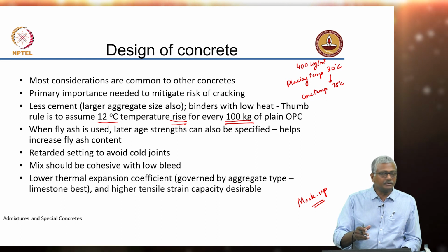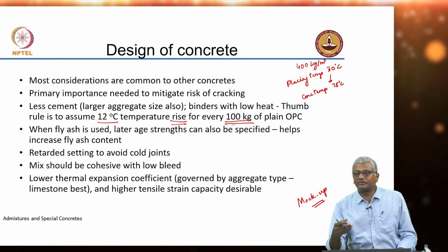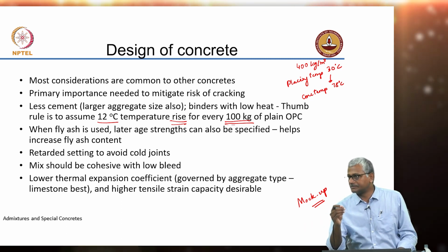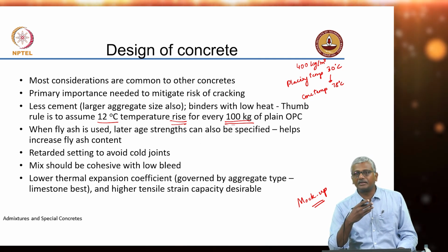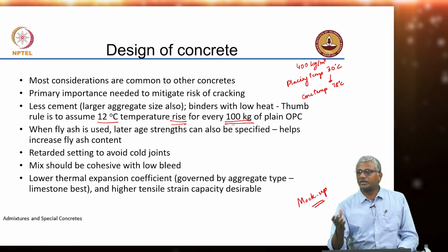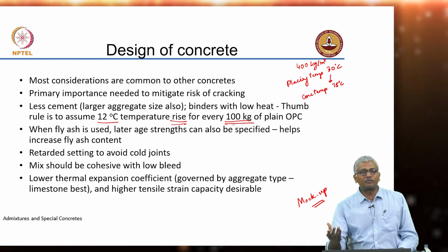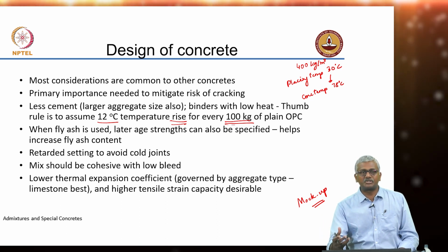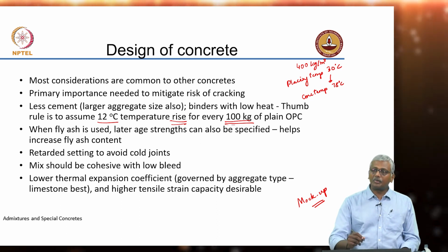It is possible to produce more durable concrete with a greater percentage replacement of the cement by fly ash or slag, even with moderate strength. We saw that in the data that we looked at during the discussion on mineral admixtures, right? Even with grades of concrete like 25 to 30 MPa, which are used for residential concrete purposes, you can still produce high quality, high durability concrete.